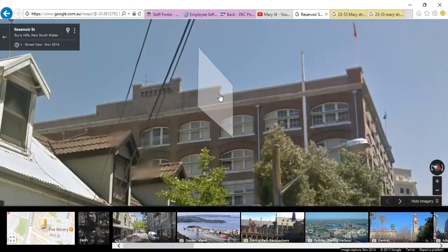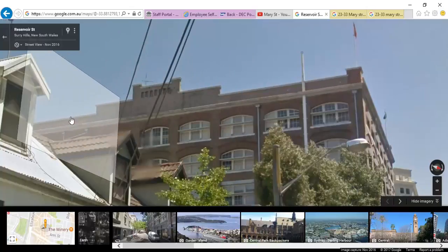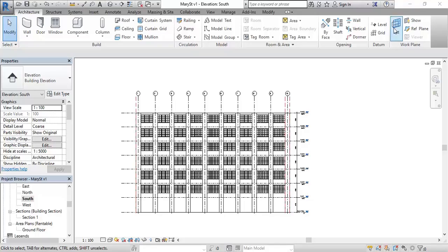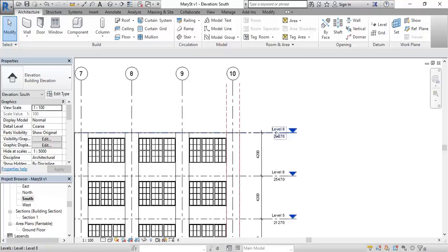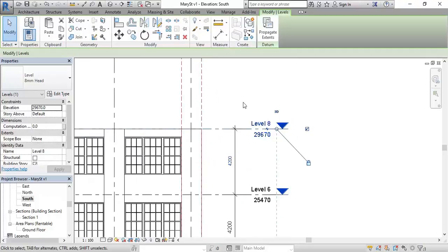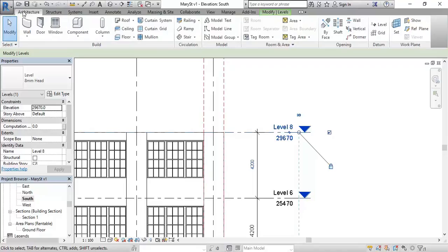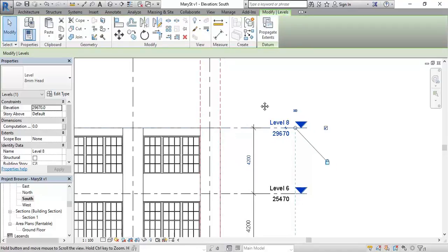But I'm not going to make levels for all the additional heights there. I'm going to just set those out manually from this level that will be for that main wall height that runs around there, which functions like a balcony wall. So to do that, I'm not going to make a new level using the level tool. I'm going to make a new level simply by selecting the level that I have already.